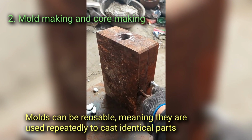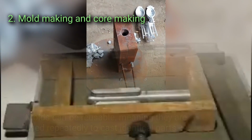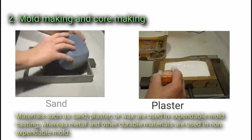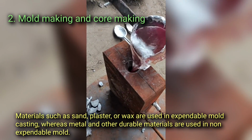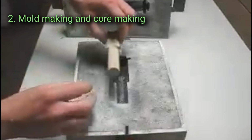Molds can be reusable, meaning they are used repeatedly to cast identical parts, or expendable, meaning they are used only once and destroyed in the casting process. Materials such as sand, plaster, or wax are used in expendable mold casting, whereas metal and other durable materials are used in non-expendable mold. Core making.